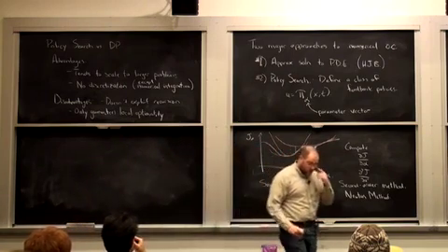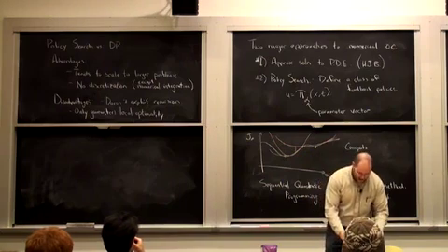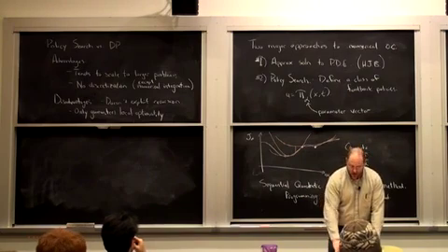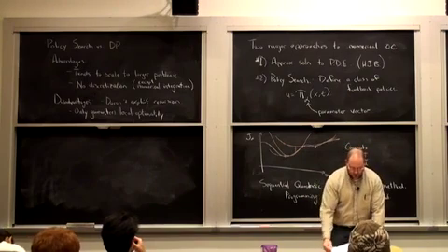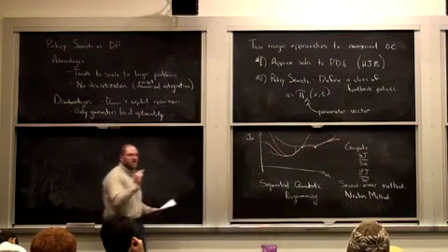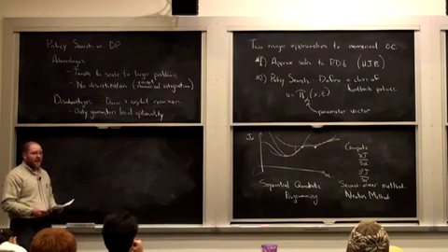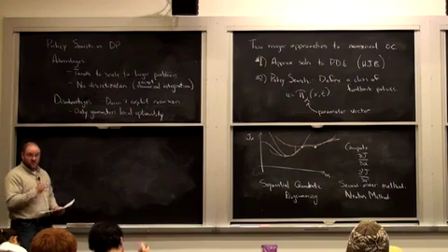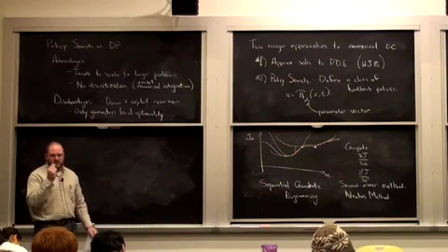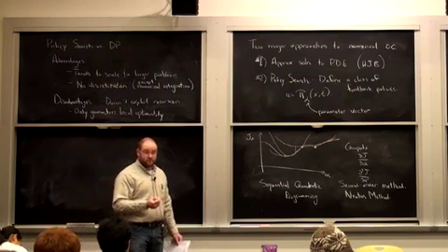The first way is literally to parameterize your control system and call SNOPT, but let's at least be smart about computing the gradients. Let's avoid asking our nonlinear solver to compute the gradients numerically, because we can compute those analytically, exploiting the structure in the additive cost optimal control equations. It turns out it's a direct and clear descendant of the Pontryagin minimum principle.